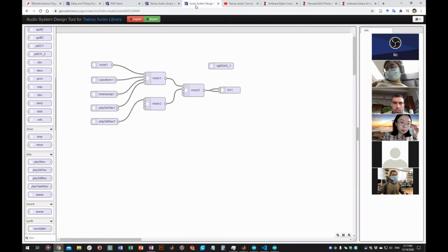This diagram, processing from one end to another, takes time, right? Especially for audio signal processing, you need buffers to store some waveform and then play out the buffers. The delay, at least in my case, is around 5 milliseconds. That might be a big delay for neural data. It's probably fine for EEG and EMG, but for spike-related things, that might be a challenge.